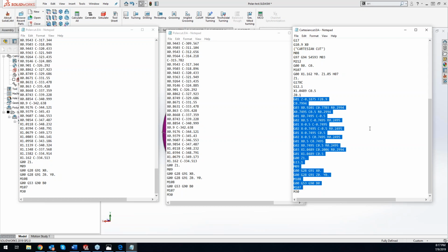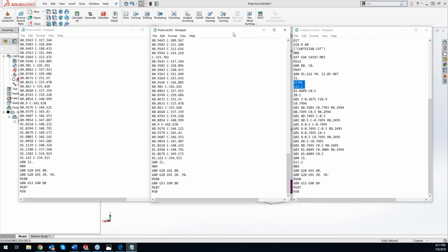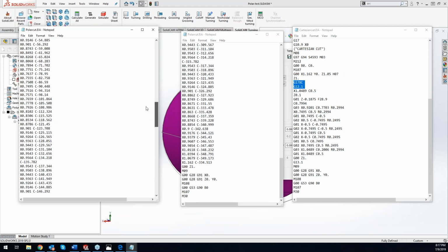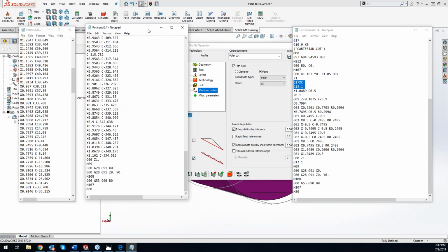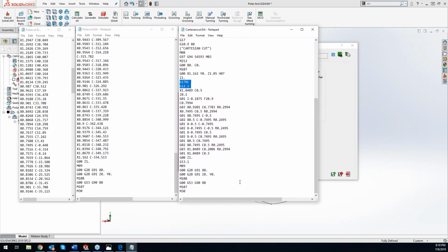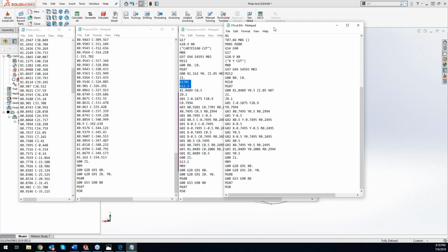So not all machines are going to be capable of doing the G12.1 or G112 or G12 polar interpolation conversion. So essentially what you're getting with the G12.1 is everything that you see on the left-hand side of the screen. We feed in values with that G12.1, and the machine's controller converts it over to what you see on the left, although we can feed it Cartesian coordinates. Let's go ahead and leave the Cartesian up there, and bring up a G-code of the XY.